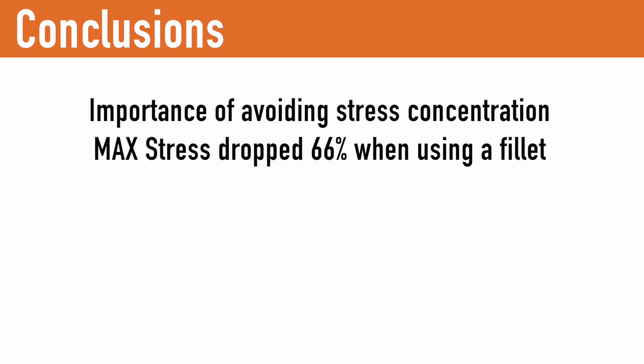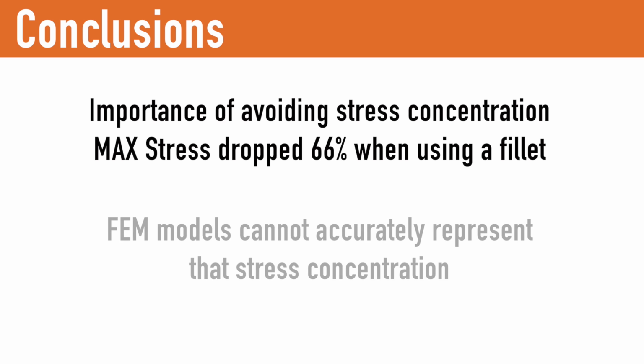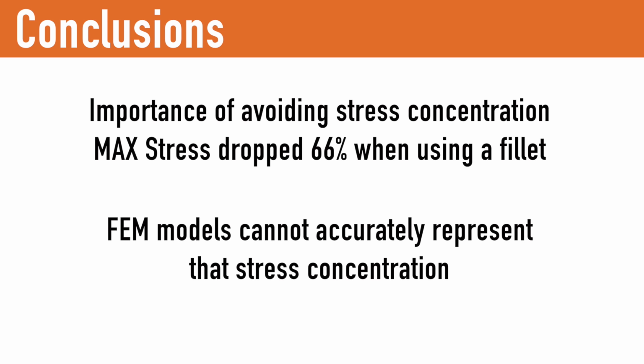This study highlights two major points: the importance of accounting for and avoiding stress concentrations when designing a part, and the inability of FEA models to represent such stress concentrations.